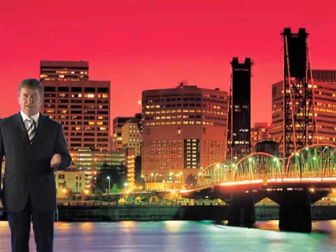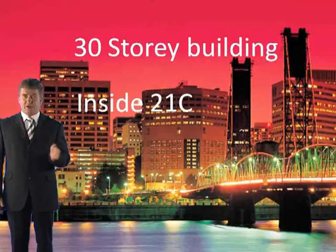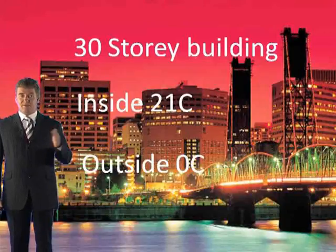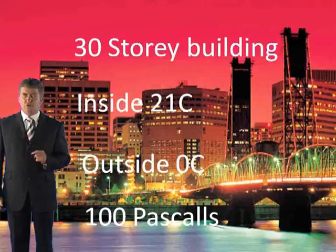For example, in a 30-storey building with a typical inside temperature of 21 degrees and an outside temperature of 0, the pressure differential at the top can be as high as 100 pascals. And you think, what does that mean? What's 100 pascals? Well, if you think about it, that's 7 times the pressure created in a post-flashover fire, which generally is about 15 pascals. So it's 7 times more pressure than the pressure created by a post-flashover fire.